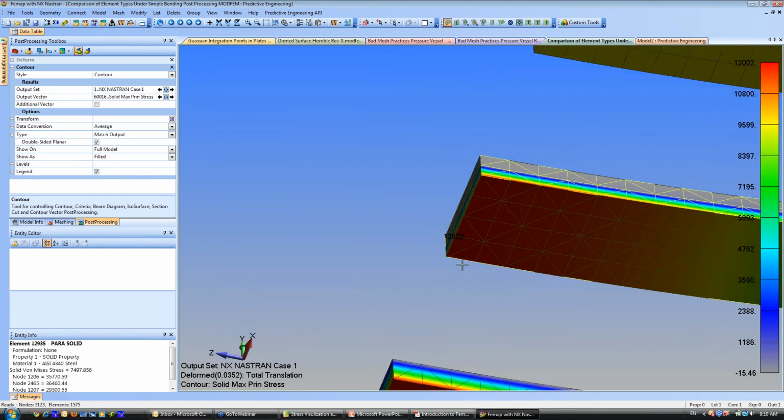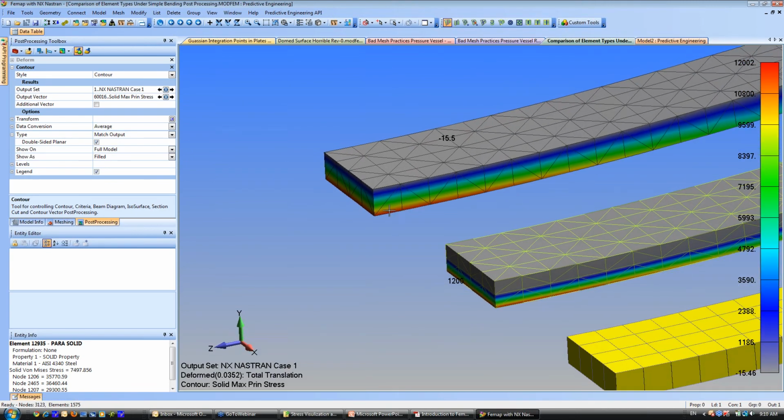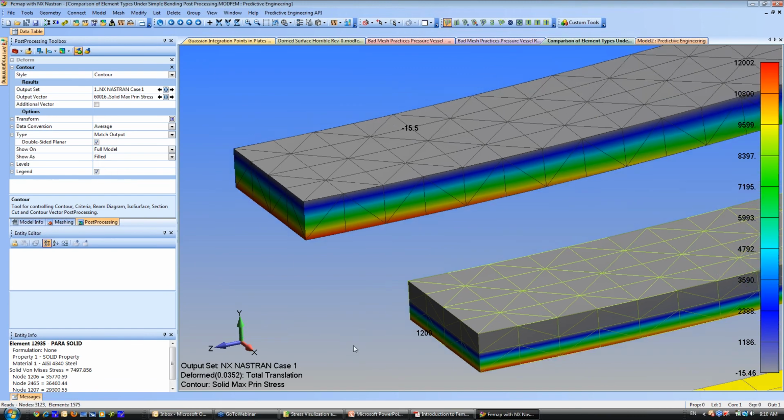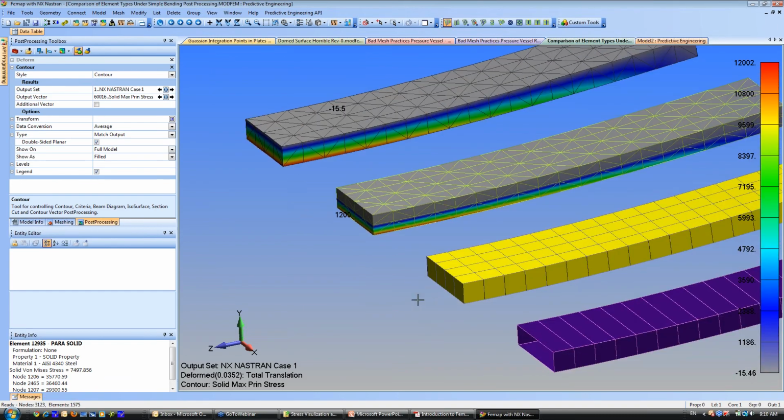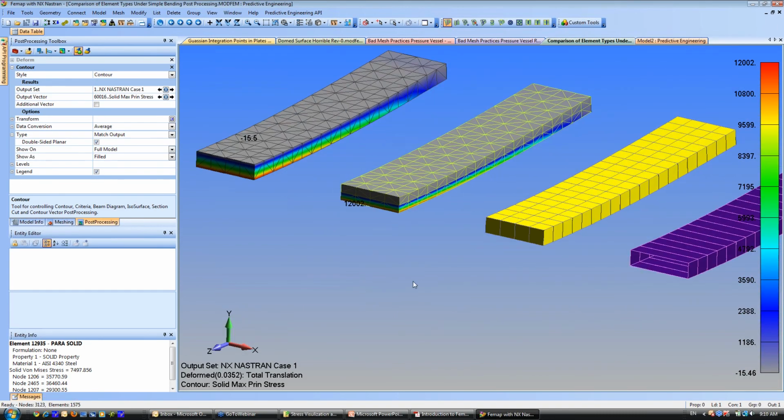Isn't it amazing, even with one element, knowing what you know about Gaussian integration? You got 4 points in there, and it's fighting. There's no central plane. It's amazing what you can do with a nicely shaped element. A nicely shaped isoparametric element would do such a great job.